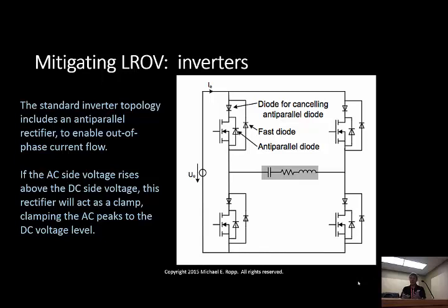What did kick in? Well, it's the power limited mechanism. I still don't get all the way up to that theoretical voltage. So it's really depending on specific inverters and what's going on. Now, I mentioned before, one other thing I should throw in here, that the semiconductor switches and inverters are heavily protected against overcurrent. There's a lot of protection here against overvoltage too. So the inverter will self-protect in ways that tend to limit the LROV.